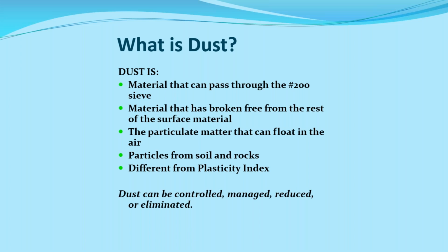If you're using a material that has a high LA wear content, say, in the 40-50% range, it's going to break down by the traffic traveling over it. And that's the reason I talked about checking your material and finding out how hard it is. How well is it going to hold up? Because if the cars are going to break it down, they're going to cause problems with that roadway, and you're going to end up maybe with more dust and more of those types of problems.